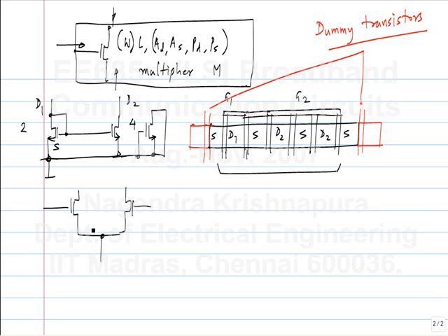Okay. Similarly, when you have cascode devices, in fact, this lends itself to even better optimization, because typically you don't need access to this node. So you don't need to be able to contact this node. So, by using a common diffusion area, you can make the layout very compact, and you can minimize the area of this node and the parasitic capacitance from that node. Any questions on this? There are lots of such practical tricks, and there are a couple of books which you can refer to. Also, when you are doing it, you can use them.